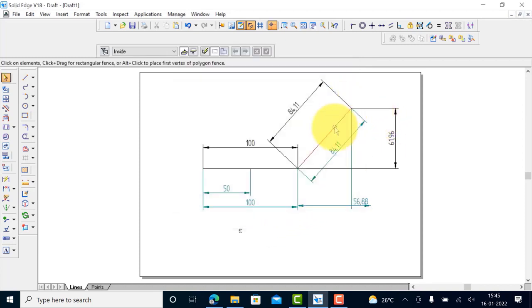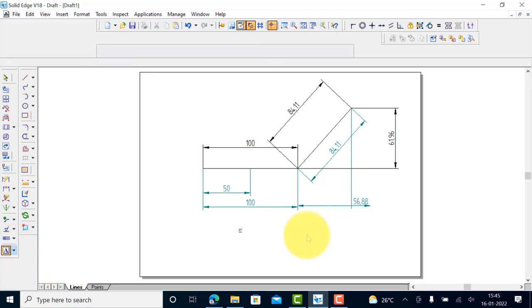And then apply. So these changes will not affect the text which you have already typed. Whereas for the dimension text, all the past dimensioning will change, but not for the text. Whatever you type afterwards, after making the changes, that will have 6 mm font.